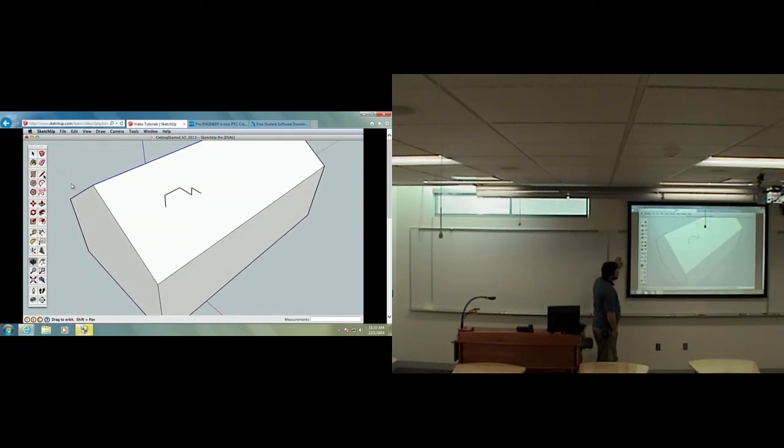To draw a chimney, we can approach it in many ways, but we'll use this method. We'll draw the side profile shape, then use the push-pull to create the full chimney. Drawing with the axis directions will help us create the correct profile in 3D space. Use the eraser tool and click on any edges you drew to erase them.